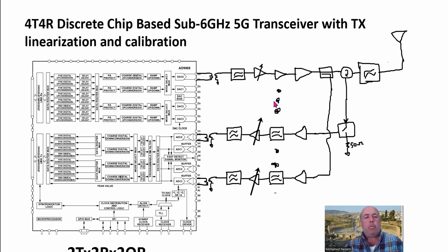Like I said, we're given this system in here. So now we can try to optimize the hardware use with the limited resources of 4 DACs and 4 ADCs. Since we might need some linear power amplifier linearization, we could utilize the system with, say, 2x2, 2 transmitters to 2 receivers, in which case we can utilize one of the receivers for the sole purpose of trying to linearize the power amplifier, like in this case in here, okay?